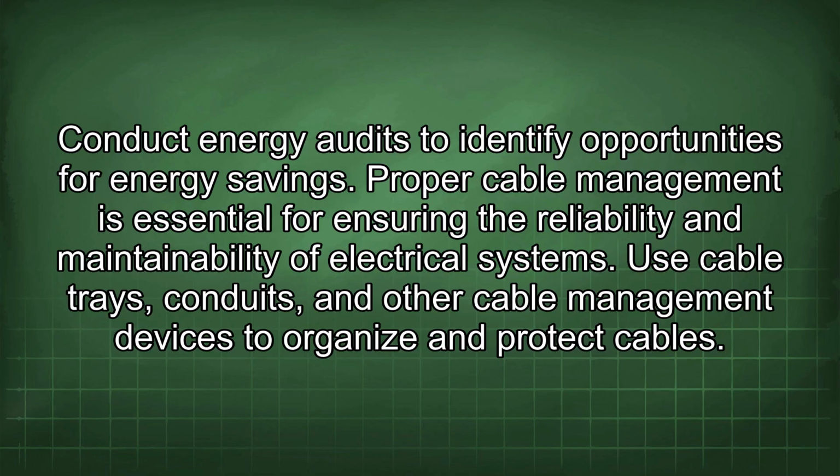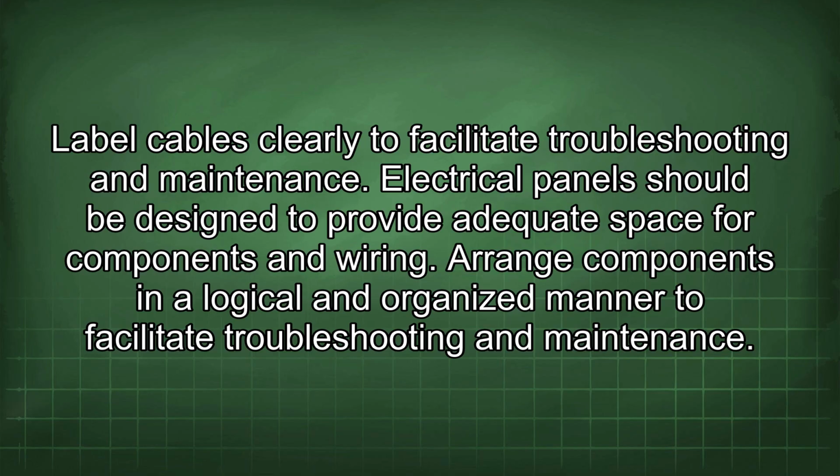Proper cable management is essential for ensuring the reliability and maintainability of electrical systems. Use cable trays, conduits, and other cable management devices to organize and protect cables. Label cables clearly to facilitate troubleshooting and maintenance.